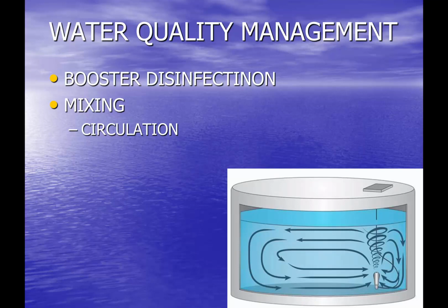So instead of having that thermal stratification or even the simple stratification associated with a common inlet-outlet pipe, these different types of systems provide a much better circulation of the water to get a really good mix, not just of the chemical that's being added, but just of the water age, so that you don't have stratification. You don't have older water in one part of the reservoir than another. You get a pretty constant water quality throughout the reservoir. In addition to maintaining water quality of the water itself, as you're adding the chloramines, these mixing systems help mix the chemical, the disinfectant, through the water much better.